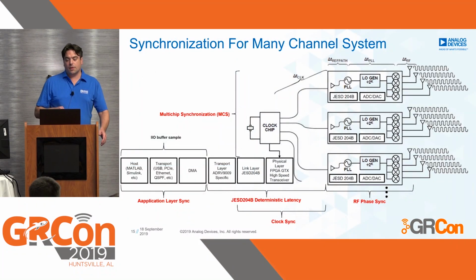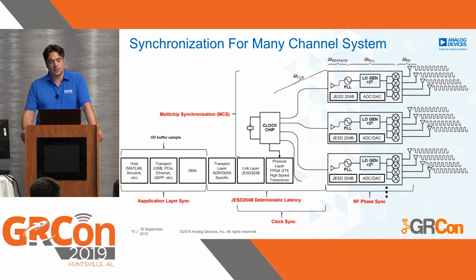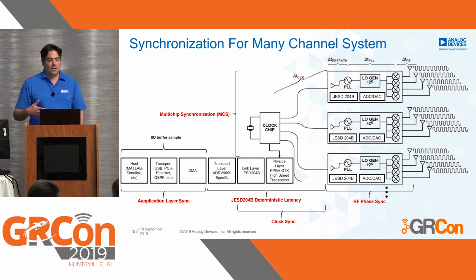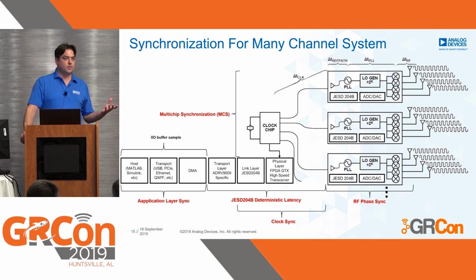But the main topic is synchronization and how we can phase align multiple of those modules in a system that can scale. There are multiple things that need to be calibrated, and they are typically done in a certain order. For example, there's the clock synchronization, where you synchronize the clocks across multiple layers in your topology.